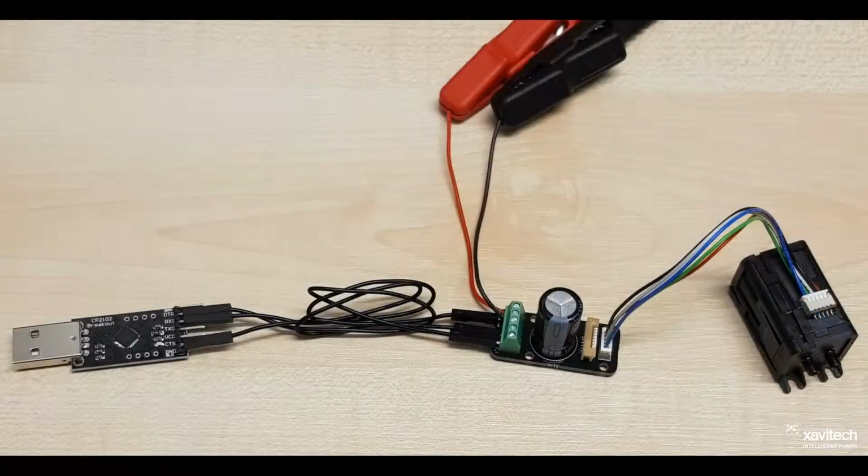In this video I will demonstrate how to communicate with a pump using the serial interface. For this demo I use a USB to UART board based on the CP2102 chip from Silicon Labs. It's to the left in this image. The logic level on this board is 3.3 volts, which means it's compatible with our pumps. The USB to UART converter is connected to the pump using our adapter PCB.